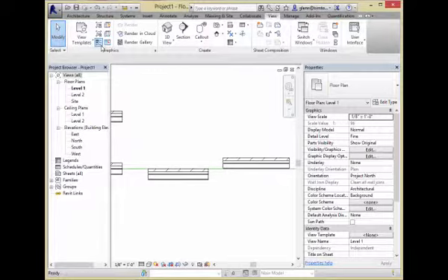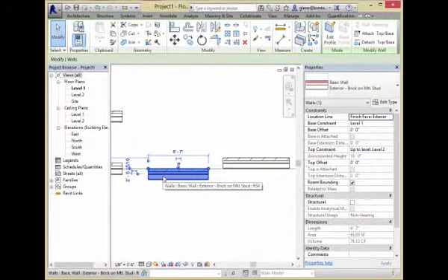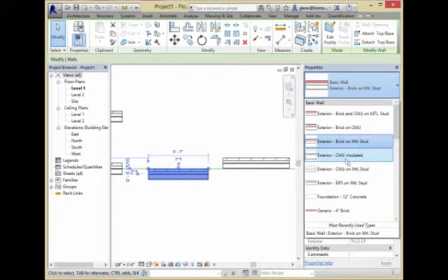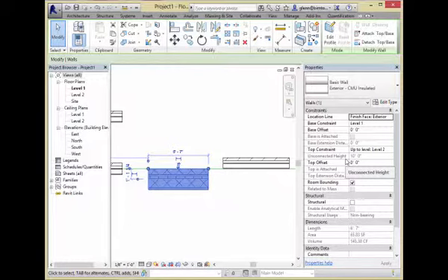Okay, so these walls, which are constructed on the outer edges, the finished face exterior and the finished face interior, are hanging there looking pretty good. If I choose that wall, I can see in the properties palette that it's the finished face exterior. If I change that wall to a different type, for example from brick on metal stud to CMU insulated, some wall type with a different thickness, notice the location line of that individual wall stays the same. So the wall grew to the inside.